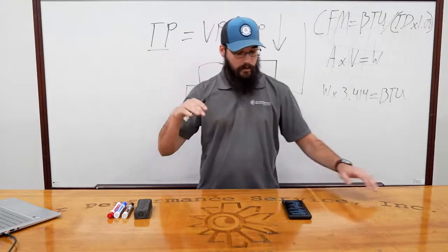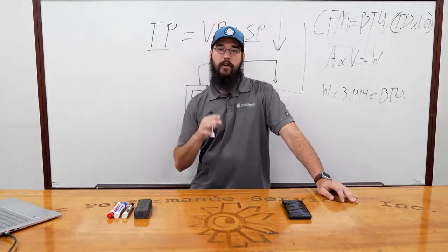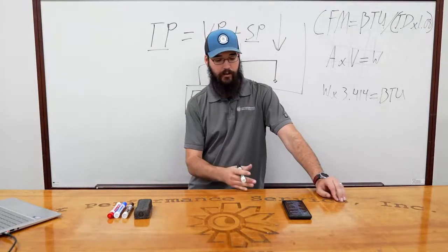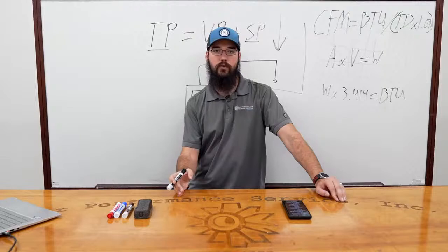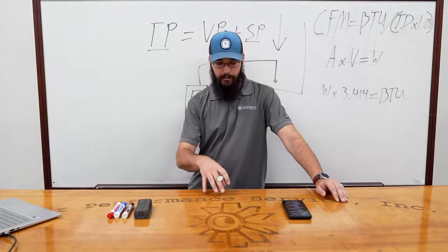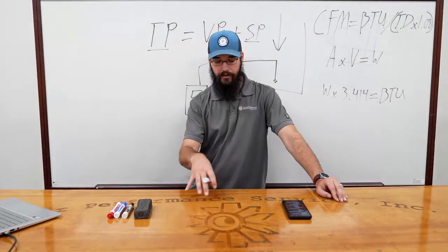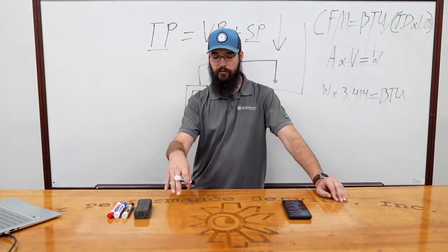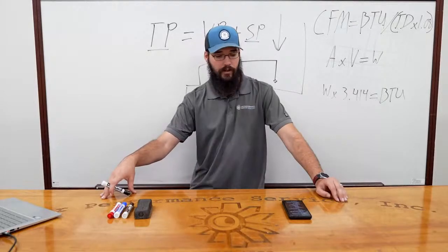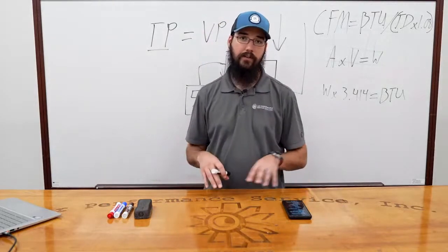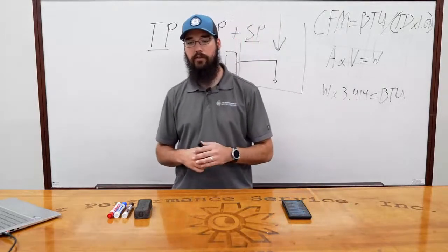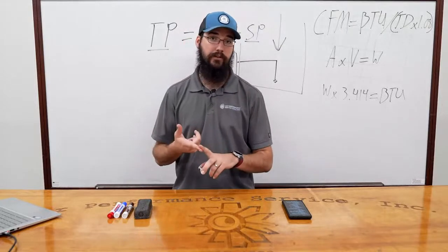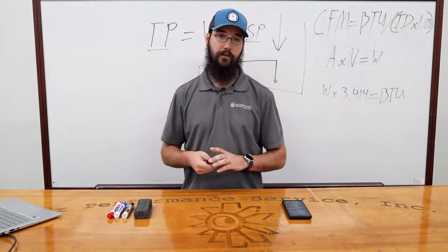Airflow. So some general things on how your airflow is going to impact your refrigerant side. You're going to see it the most in your evaporator. Now, keep in mind, your condenser is dependent on your evaporator load. There are other things that affect a condenser, such as, is it dirty? Is the fan having a problem? There are physical attributes of the condenser that can affect the head pressure, the subcooling, things of that nature.